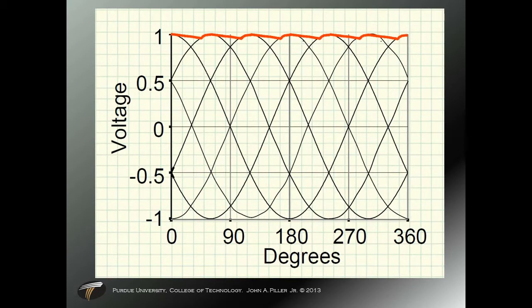And then here is the signal for the bridge rectifier output with a capacitor to reduce the ripple. Again, the black lines are the 6 phase voltages. The red now is the DC output without the ripple. This configuration, we can use as an input to a microprocessor controlled system of a variable frequency drive. Now we need to figure out a way to take that signal and control an output frequency.